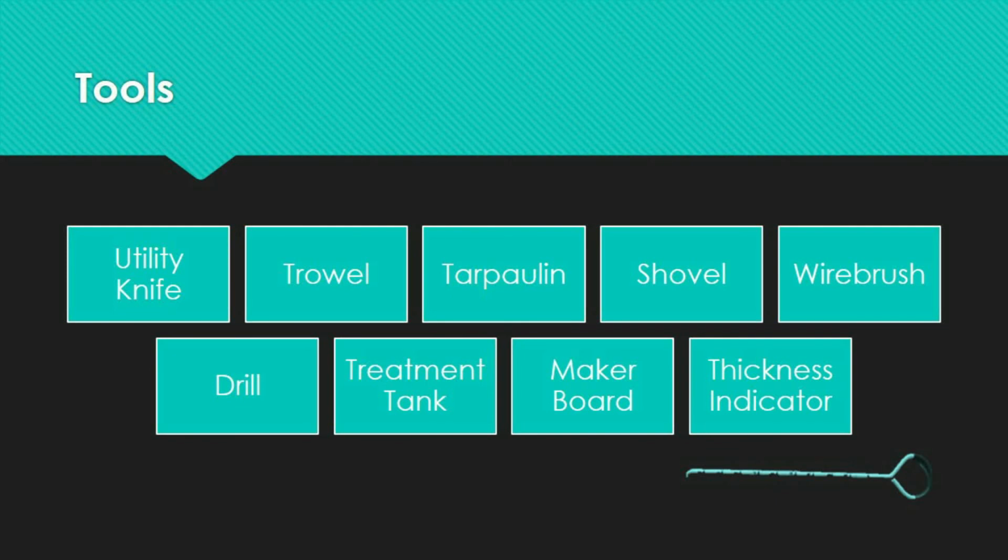When the tool is placed into the drilled hole, the indicator's toe will penetrate the rotten wood, and resistance will be felt when the tool is removed and the toe meets sound wood. On one of the two graded scales on the tool shaft, the thickness of the sound wood, or the shell thickness in this case, can then be read. When one scale is used in a hole drilled at 45 degrees, the other is used in holes drilled horizontally.